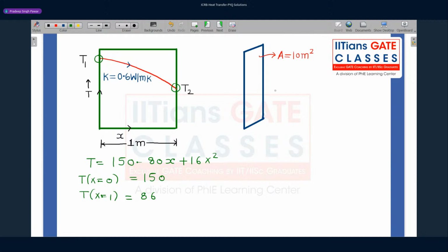Okay, now let us see what he's asking us to find. If we take this entire wall as our control volume or as our system, whichever way you feel convenient, we can then apply the energy balance, the law of conservation of energy, for a particular instant. It says the rate at which total energy is coming inside the system, minus the rate at which total energy is going out of the system, plus the rate at which energy is generated within the system, is equal to the rate of change of energy stored within the system.